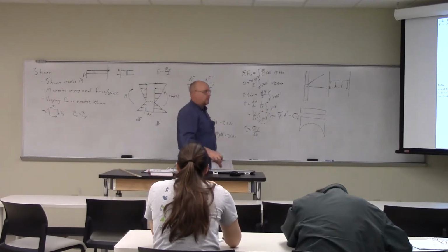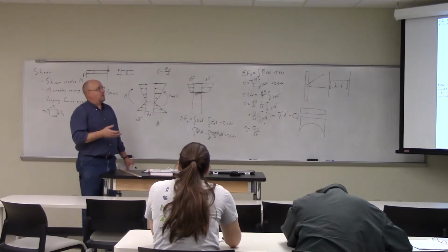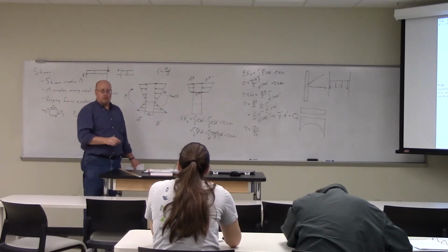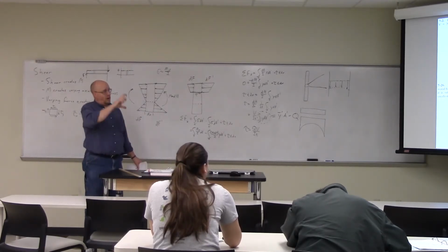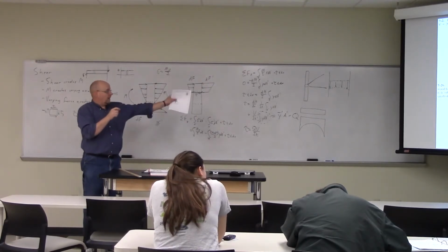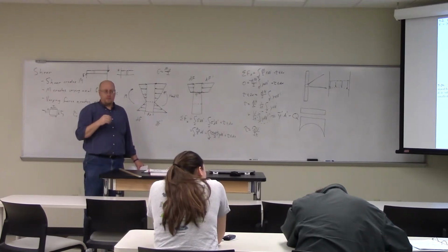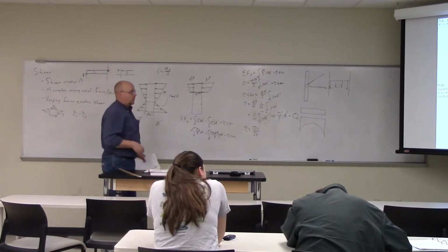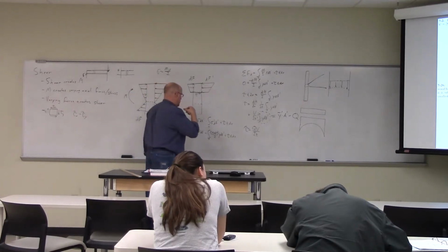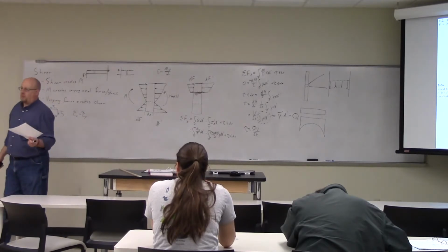So for instance, that I-beam there. You notice the center web is long, h is much greater than t, so we're good on that standpoint for the uniform distribution of the shear stress. And the sides are perpendicular to the cross-section, so we meet that criterion as well. So for the I-beam, and for the square beam below it, both of those work. Okay, does anybody have any questions before we jump on to the problems?